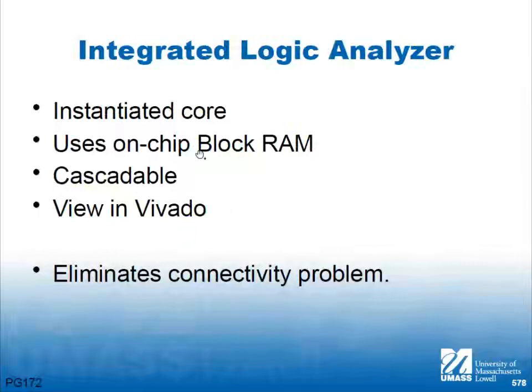So they call it ILA in Vivado, which is the Xilinx product. They call it ChipScope in the Intel product, right? It connects to their Quartus system. We're only going to talk about this because they are virtually the same. So this is a piece of logic that you get from the manufacturer that you compile into your FPGA, and it uses the otherwise unused block RAM in the FPGA. FPGAs have tons of memory in them, and rarely do you use all of it. So the extra, you use that for the logic analyzer.